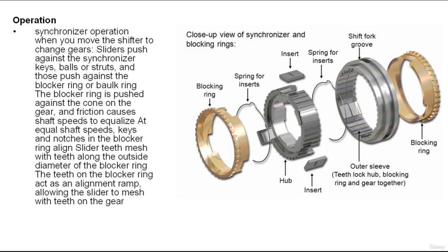When the blocking ring and gear shoulder come into contact, the grooves on the blocking ring cone cut through the lubricant film on the first speed gear shoulder and a metal-to-metal contact is made. The contact generates substantial friction and heat. This is one reason bronze or brass blocking rings are used. A non-ferrous metal such as a bronze alloy minimizes wear on the hardened steel gear shoulder.